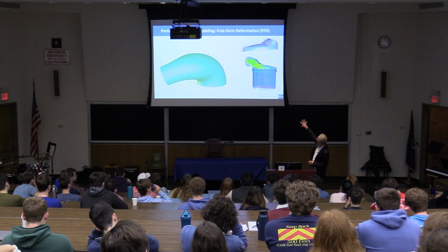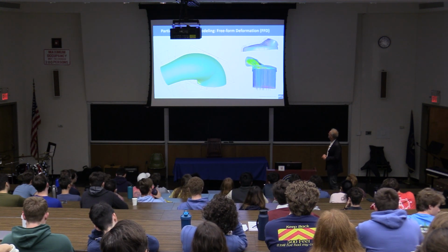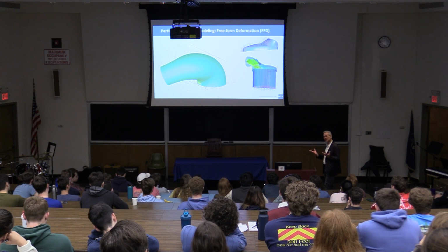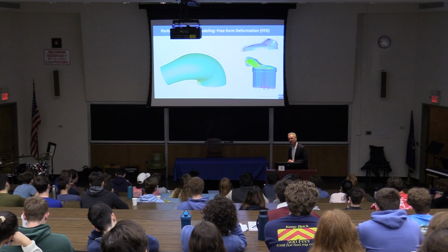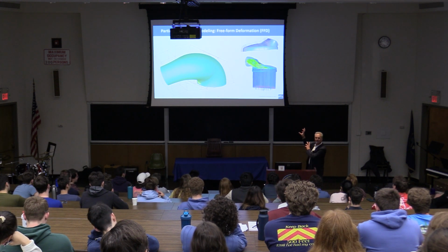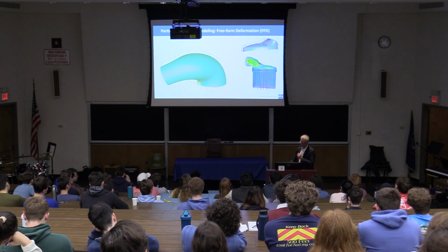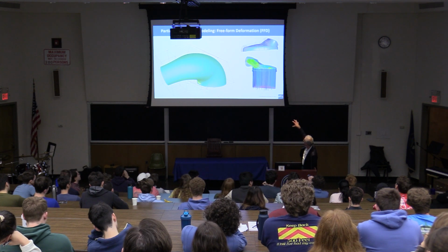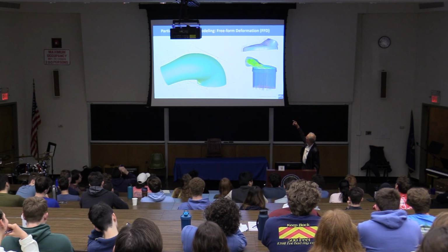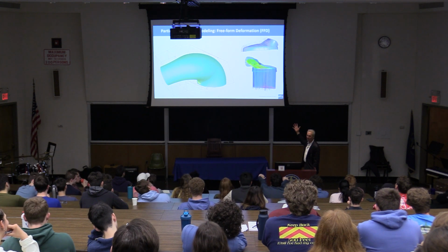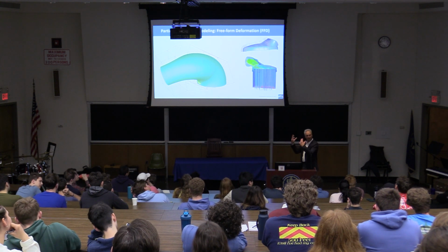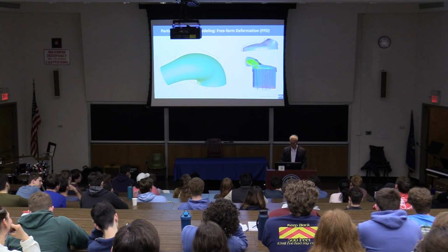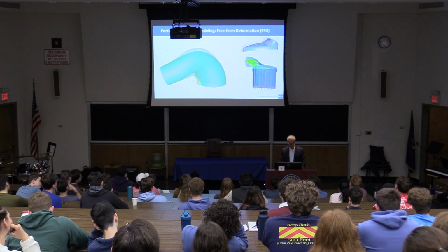The example over here is from a Stuttgart-based, southern part of Germany, engine manufacturer. They have nice cars with a little, so to say, emblem that looks like a star. It's a catalytic converter. I'm not allowed to say which one it is. And as you can imagine, we changed the geometry with this freeform deformation, and to go into the catalytic converter, you want to have a very homogeneous flow field. So another example, not so much from naval architecture, but it nicely shows how to use those freeform deformations.